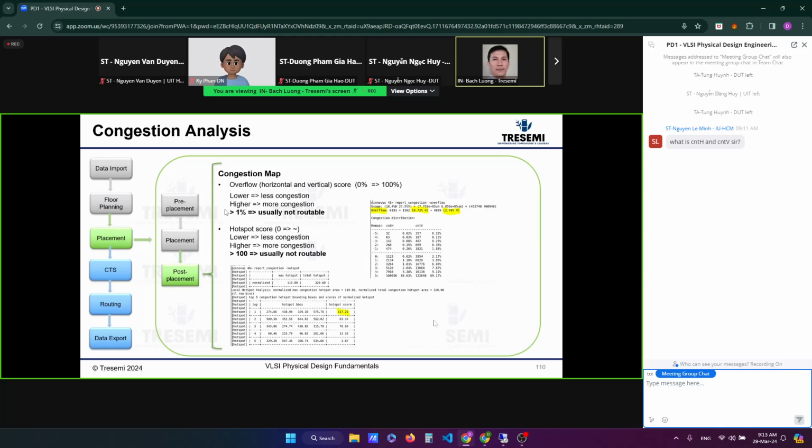These are the numbers for the Innovus tool. If you use another tool, it's going to be different. The normalization will be different. This class is taught based upon Innovus, so this is the number I've used. If you use another tool like Synopsys, the score may be different. They normalize differently. So remember, this is the Innovus score. Don't take this number and use it on another tool, because each tool scores differently.